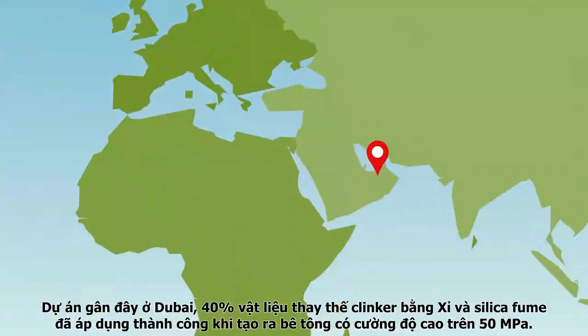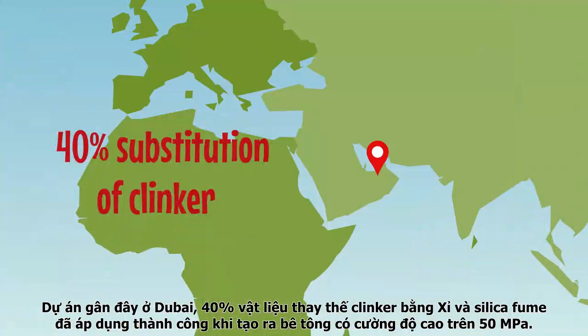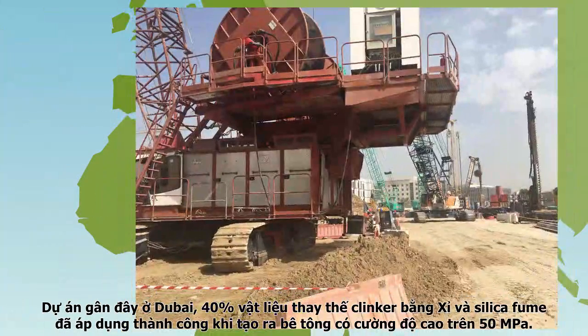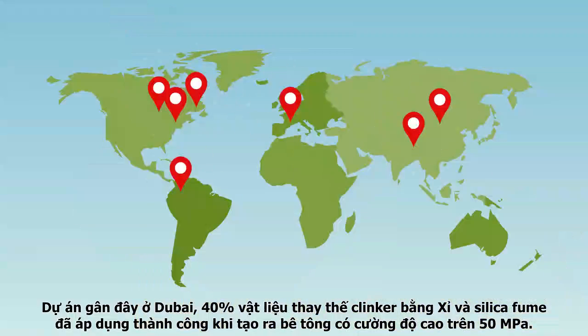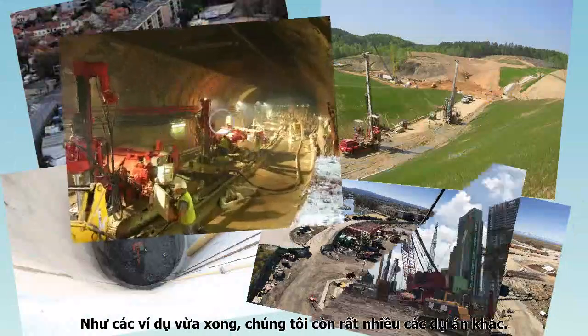On recent projects in Dubai, a 40% substitution of clinker by slag and silica fumes was possible to achieve a high-performance concrete with strength over 50 megapascals. Like the examples mentioned before, we have many more to give you.